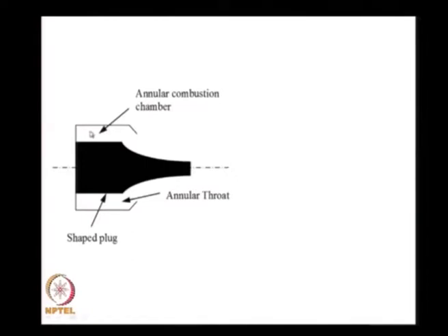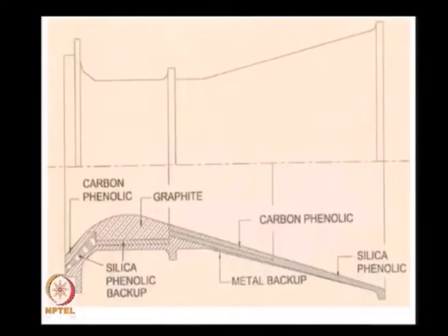The flow comes. The flow in these cases, you generate it in an annular chamber instead of having a chamber over here. I push the flow on to this inner surface, and the inner surface guides the flow, the outer surface is free, therefore I can have any type of expansion that I want. It is still not used in practice, and this summarizes what we learnt about nozzles.